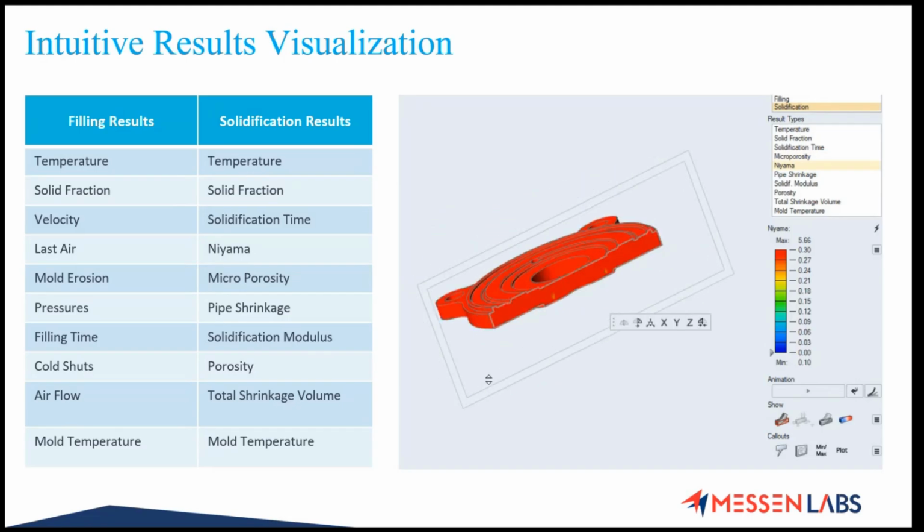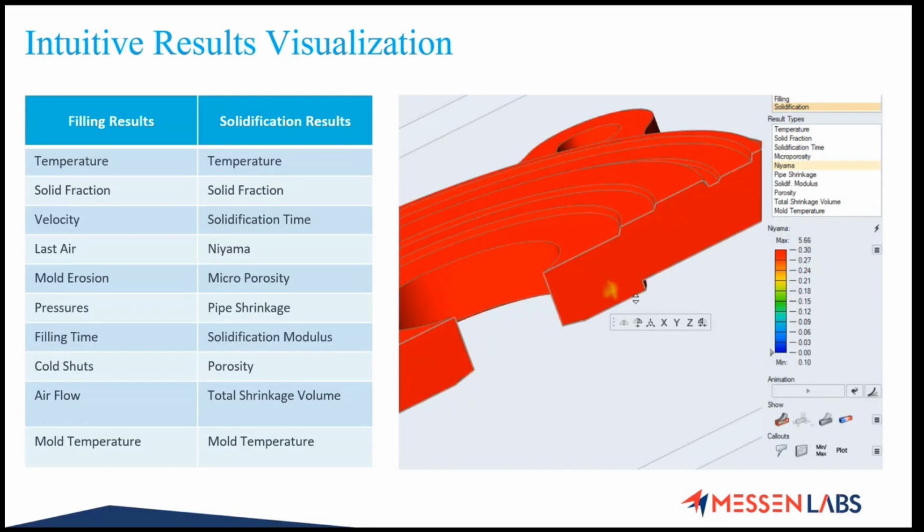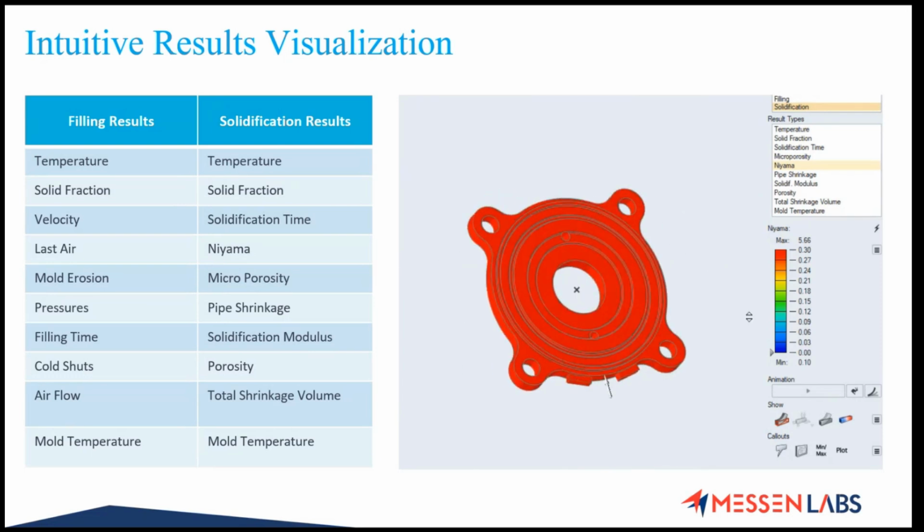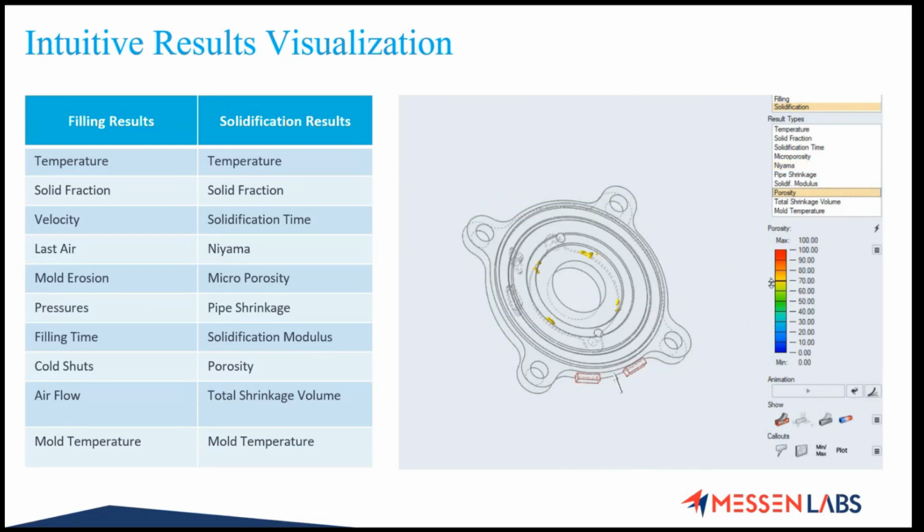In solidification results, we can see the solidification time, microporosities, shrinkage, solid fractions, Niyama criteria and more. You can also animate and visualize these results in your model.